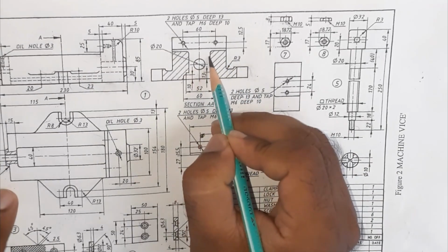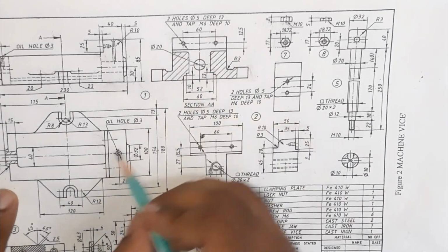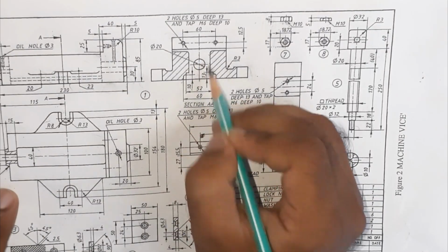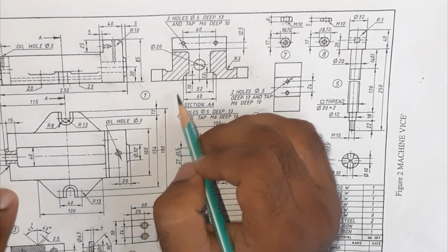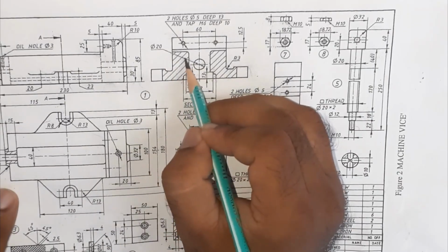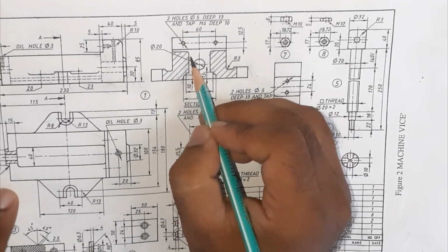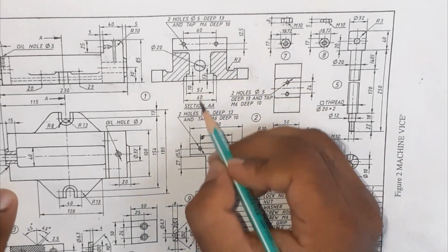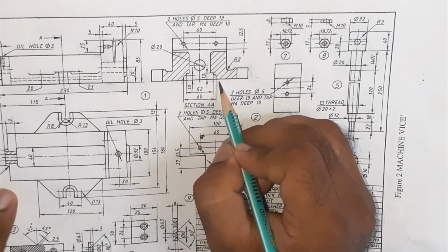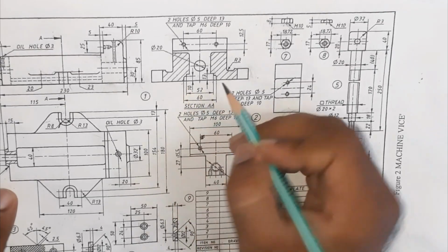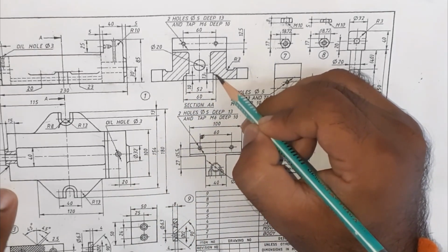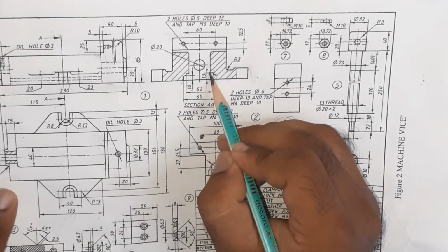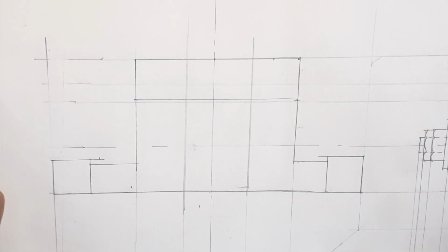What will be this distance? We will get it from the top view, that is 40 mm. So from the center 20 and 20 mm. The total is 100, so 100 minus this 40 is 60, so 30 and 30 mm. Then draw a straight line like this, and also from the bottom a length of 60, with a height of this, that is 10 mm. Next, a length of 52 and a height of 13. So these two things we have to draw.